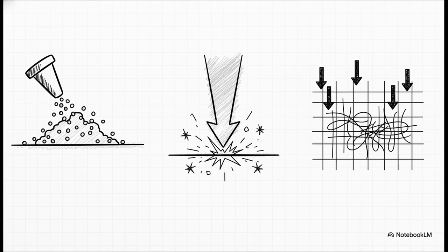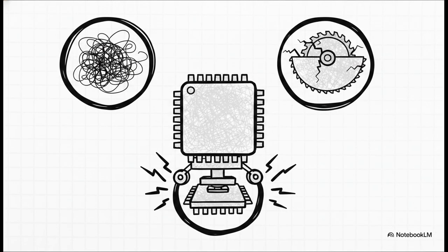And when we use ion implantation for dopants, it actively causes lattice disorder and amorphization. Even after annealing, you're often left with residual defects that degrade performance. Finally, we reach the back end, but honestly, the atomic scale damage doesn't stop there. In fact, defect accumulation sort of peaks right here.